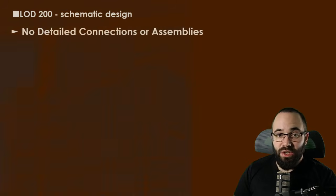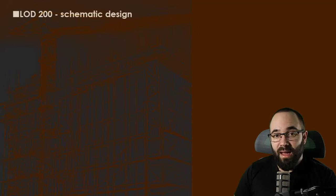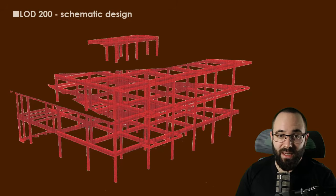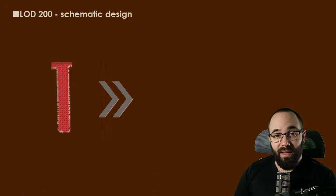No detailed connections or assemblies. So unlike LOD 300, which we'll talk about in a moment, LOD 200 does not delve into intricate connections between elements. It focuses on individual components rather than their interrelationships.